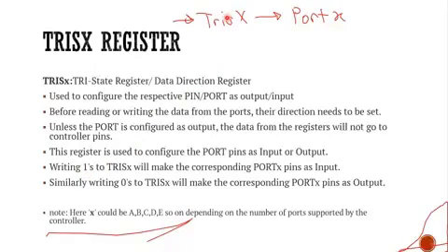How many pins? If you want to use up to 4 bits only, we can set 4 bits from TRISX as input, by writing all 1s, all 4 bits 1. Okay, like this.